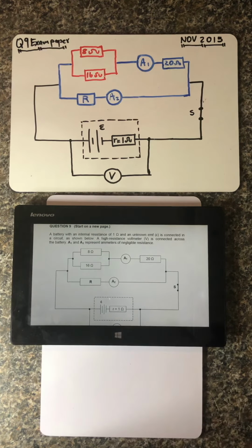So now, ladies and gentlemen, within a battery, you might have an internal resistance. Let's say, for instance, the voltage of each cell was 1.5 volts. Now, because we talk of a battery, which is the combination of those two cells, that means we've got 1.5 plus 1.5, which equals 3 volts. So the combination of those two cells, which forms a battery, has 3 volts. What is meant by internal resistance, which is represented by a small r, in this case, is 1 ohm. It could be 0.5, it could be 0.8, whatever number it is.